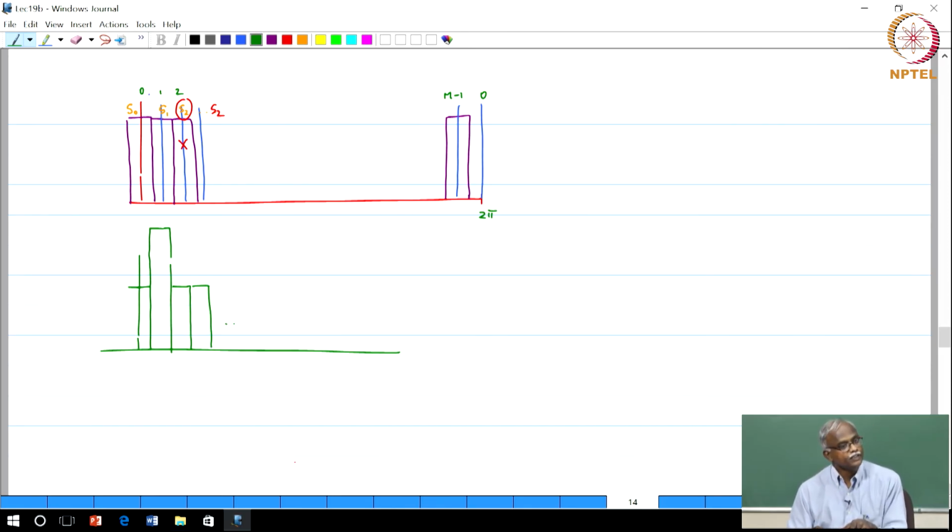Now, how do you achieve this? You could scale S1, apply more power to S1 and then pass it through a normal DFT, which basically means that you are transmitting more power on this channel. Now why would you transmit more power if the channel is already good? In that case, if this was a 4 QAM, you may be transmitting a 64 QAM on this particular carrier. That is how you achieve capacity. This is related to a concept called water filling. Water filling basically means that when certain channels have a good signal to noise ratio, you allocate more power to them compared to the other channels.